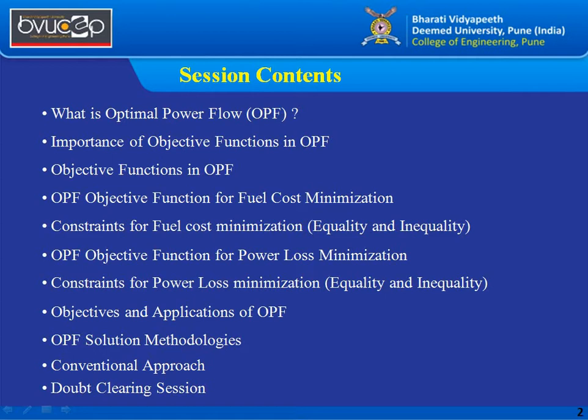Now, what is optimal power flow? Let me first quickly tell you the difference between the normal load flow analysis and the optimal power flow analysis. In the normal load flow analysis, the control variables that we consider at any particular bus, because we consider a bus as a node for load flow analysis, are predetermined or pre-specified before performing the load flow analysis. Here I am limiting myself to AC load flow.